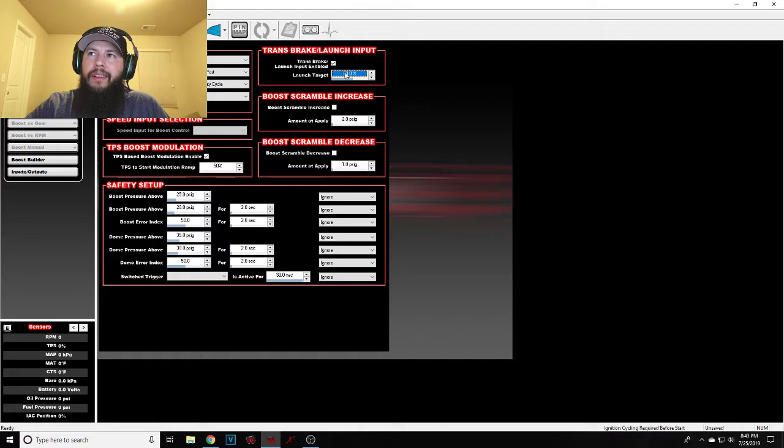But let's say you want 5 psi all the way down the run, you're not going to be at 60% duty cycle all the way down the run. I can almost guarantee you that. So if you want to launch with 5 psi and do 5 psi all the way down the track, this duty cycle is not going to be the same. And so when you're doing a target-based setup, you can see that. You'll be able to see the drastic differences in duty cycle between launch control versus going down the track.